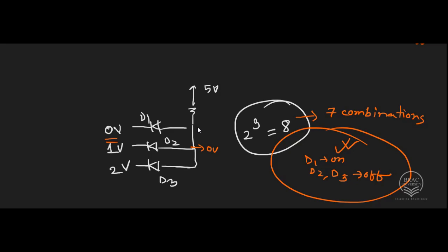As you have seen, in these cases where the input voltages have different values, we have analyzed the circuit considering different scenarios. Sometimes we have assumed that D1 is on, D2 is off. Again, we have considered D2 is on, D1 is off, all the possible combinations. So we do not actually know what may happen. We have considered different scenarios. This is called the method of assumption, or method of assumed state, you may also call this.